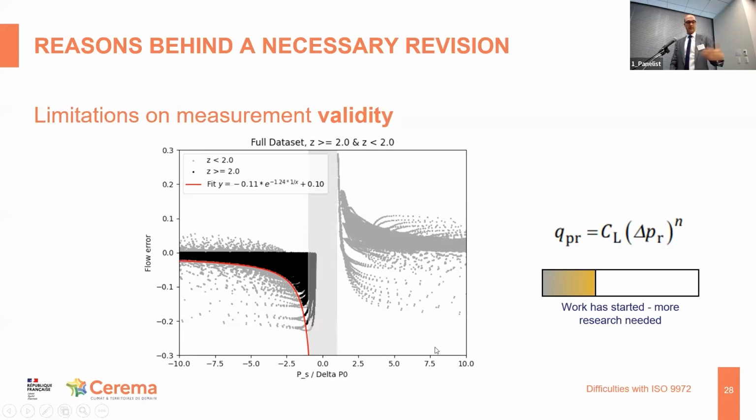And what we did then, we thought, okay, this graph is a bit messy. Can we show just the configurations which occur very likely in reality? A lot of these simulations have most of the leaks on the windward side, and none, or a very small portion, on the leeward side. If you have a square building with wind blowing from one direction, one facade is the windward side, and three facades plus the roof are the leeward side. So it's very unlikely that all these leaks are only on the windward side.